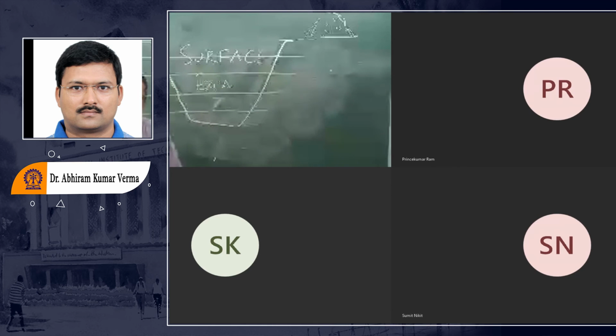I had plotted for the underground excavations. Now for the surface excavation, how your stress field is going to change, you have to identify at what point the stress density, the number of lines passing per unit area, is more. If it is more, it means that point is more vulnerable to failure.